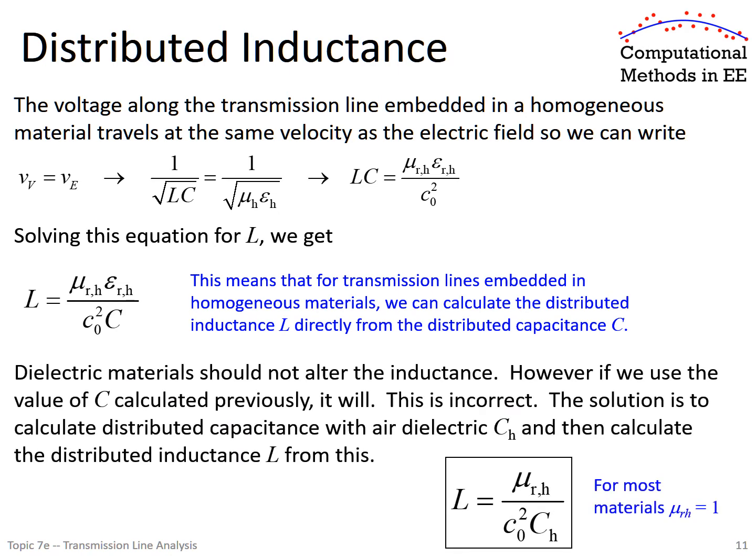And the answer is, it would be, but physically, the inductance does not see permittivity. So what we have to do in our simulation is remove all of the materials, just make it all air. In fact, we could make it any permittivity we want to. We just have to make it homogeneous. It's convenient just to put all air in there.